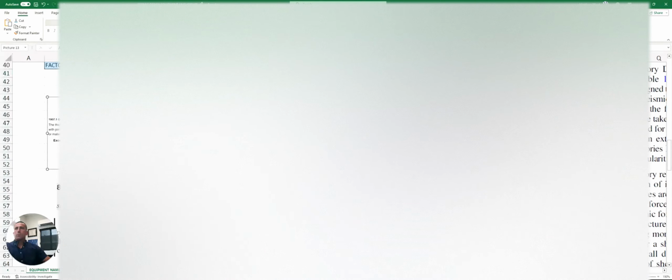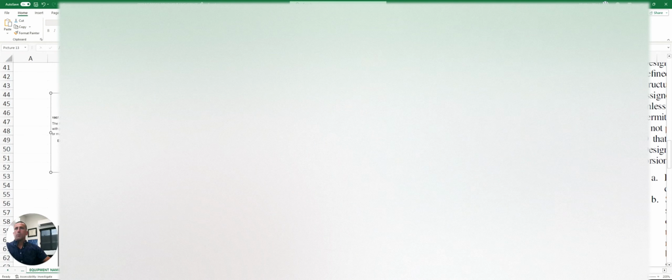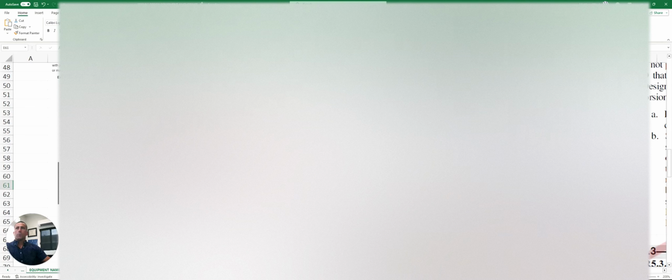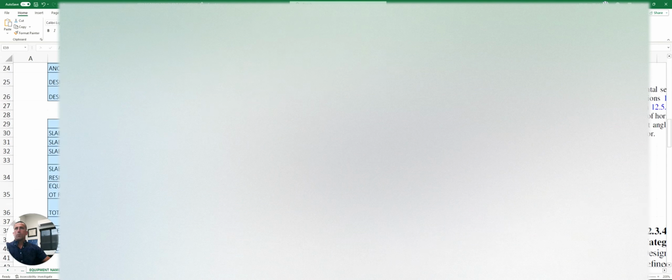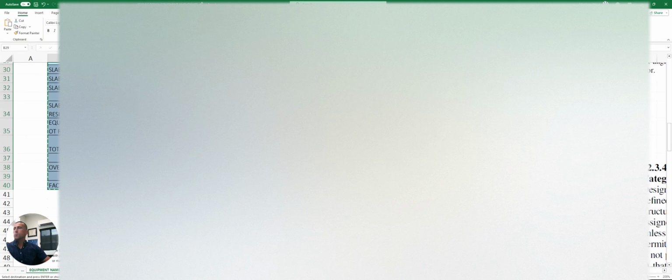And here are just a few screenshots that provide some input on slab design. So from the California Building Code, 3.5 inches minimum, and then it gives some provisions regarding vapor retarders and when they are not needed. And then as far as minimum reinforcement ratios, here's some information from ACI. I like to put little screenshots of information, and it helps me understand where I got information from. So I'm going to copy this out of the Excel spreadsheet, and I'm going to put that into my report.